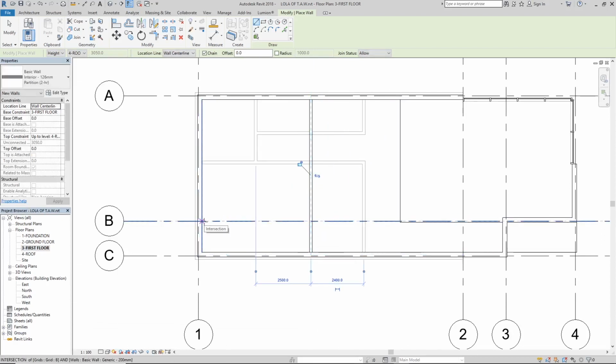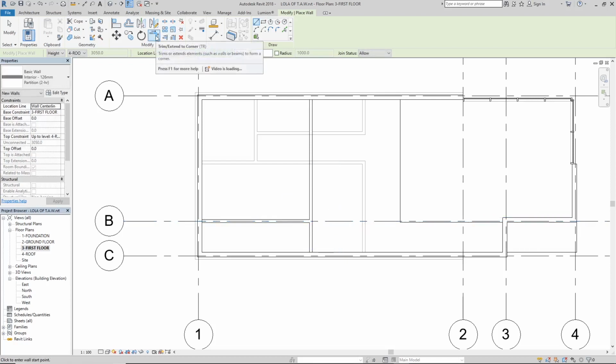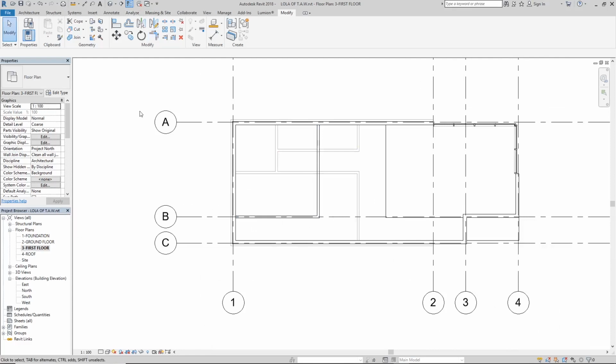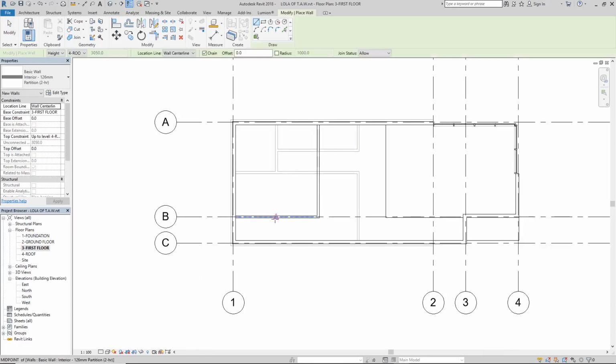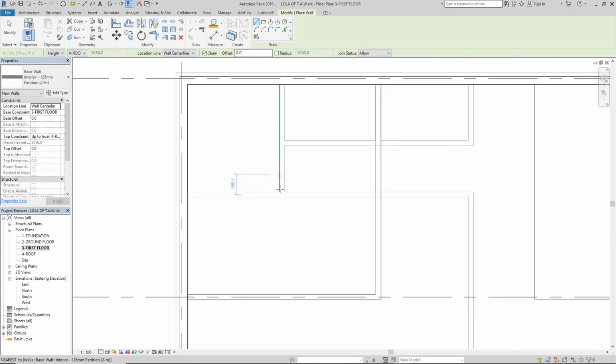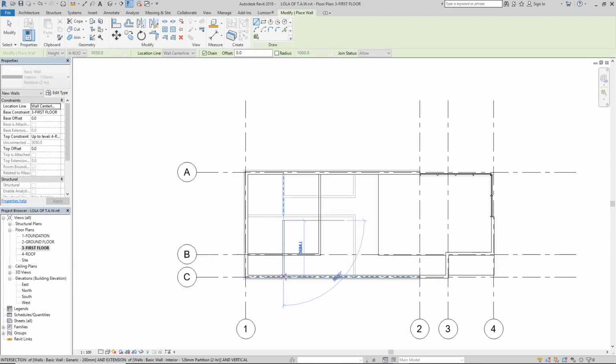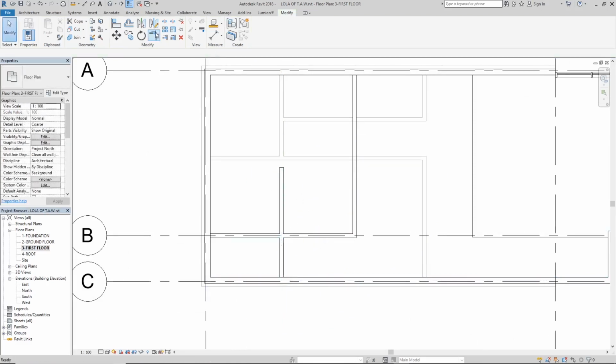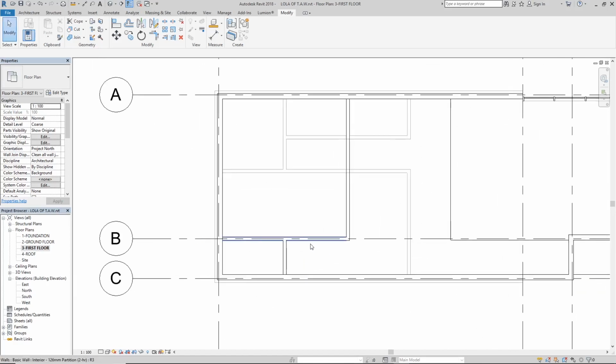And maybe we'll just follow this line and just let the walls come like this. And then we'll click our trim and extend tool and just put it like that. And maybe we'll type WA again so that we can have another wall that aligns with this one. Now we're just going to put it down here. So just going to trim and extend tool, come down here, click on that and that, and do that.